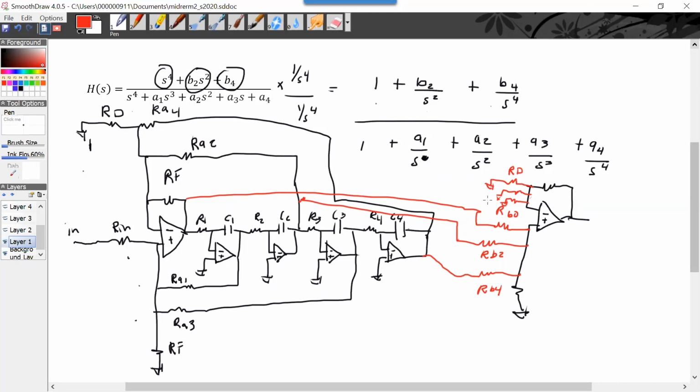And then, now it might seem that it's obvious that's out, but then you need to label that out. No need to come up with the values. But yeah, you need 4 inverting integrators. They need to be summed back properly. Sometimes people bring the feedback to one of these nodes where no, it's either coming in on the negative node or it comes in on the positive node. And a voltage can't just connect to a line or a node, it's got to connect through a resistor.